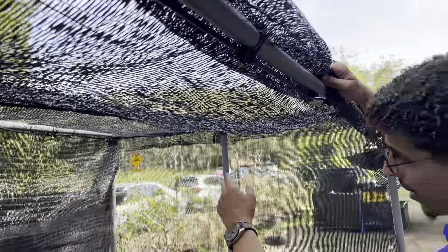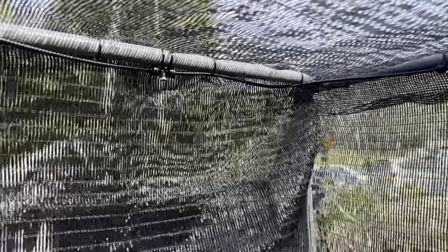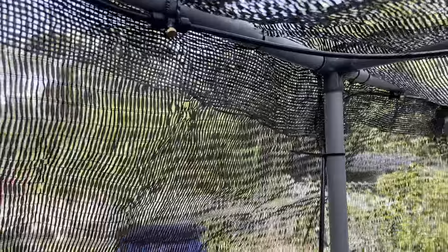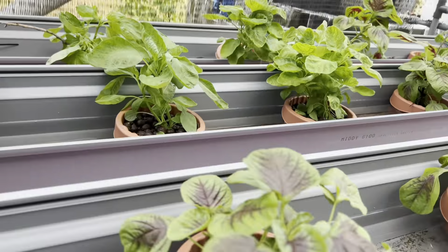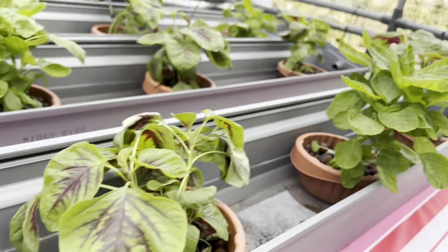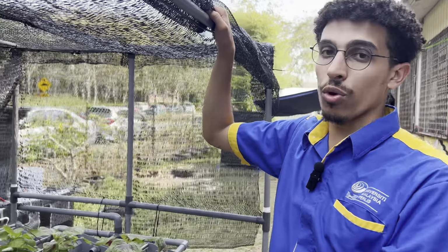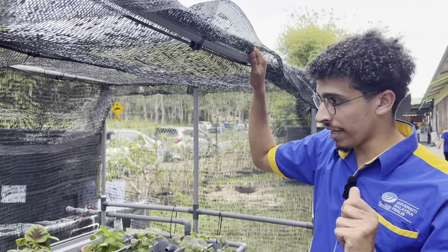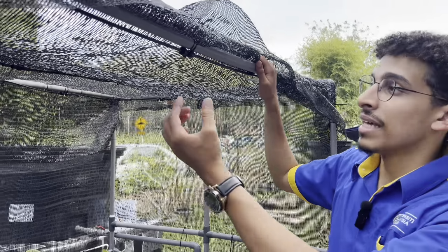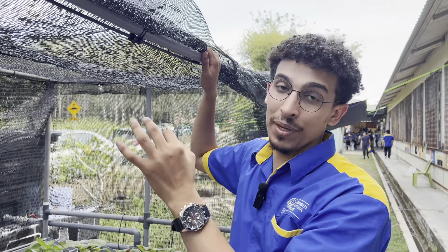So basically we have designed a system with 13 nozzles to ensure that all the plants are being covered, and through our design we ensure that there is no overlapping of the mist, because too much misting can affect the plant. So we try to balance between giving the plants a good, cool environment, and not overwhelm it with the misting. We are using this pump which can give 0.8 megapascal, which is strong, because the mist needs a strong pumping pressure to give us the best fine mist.